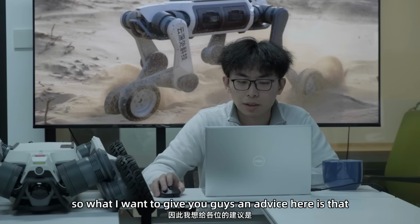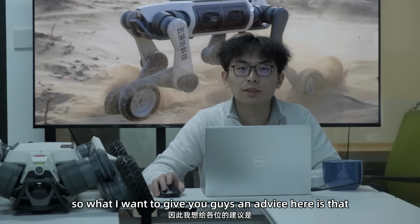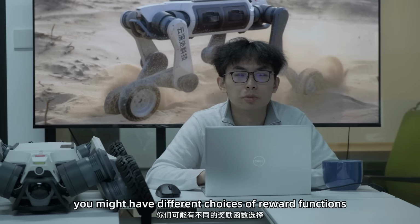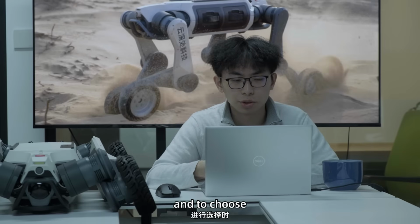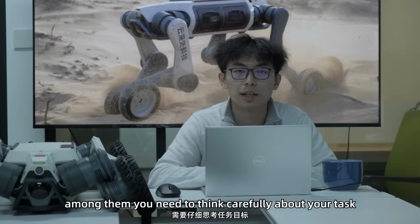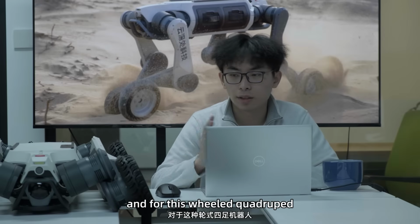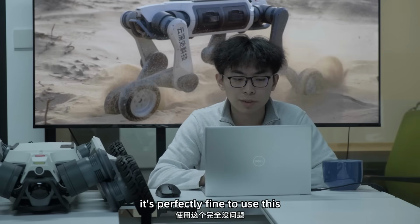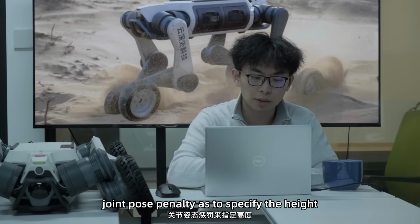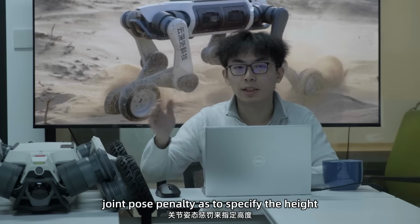What I want to give you as advice here is that to do the same thing, you might have different choices of reward functions, and to choose among them, you need to think carefully about your task. For this wheeled quadruped, it's perfectly fine to use this joint pose penalty to specify the height.